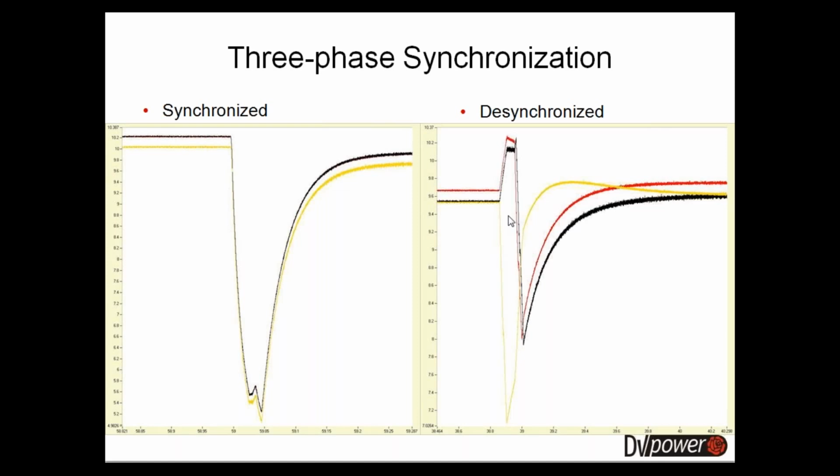The second biggest problem of desynchronization is when you have very, very large transformers or sets of three single-phase transformers connected in one three-phase system, which are operated by different control mechanisms and by different tap changers. So this can indicate that the three single-phase transformers are not in sync with each other, and that the control linkage between the three needs to be readjusted.